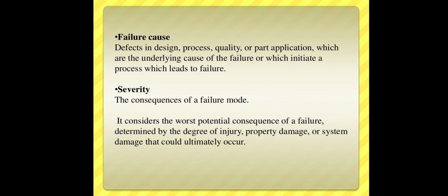And severity is the consequence of the failure mode. It considers the worst potential consequence of the failure, determined by the degree of injury, property damage or system damage that could ultimately occur. Severity is just a consequence of failure mode, that represents the consequence of failure mode. It might be degree of injury, property damage or system damage that ultimately occurs.